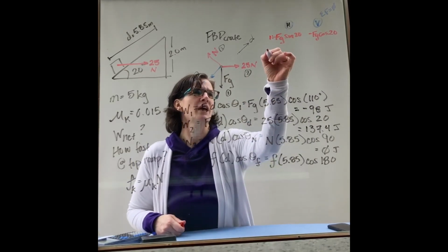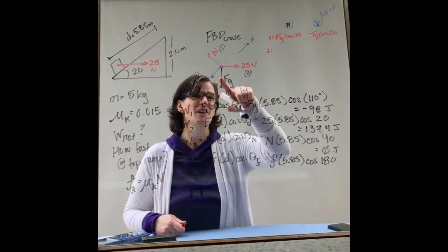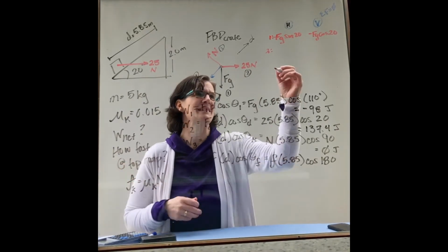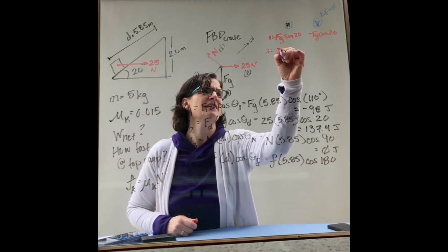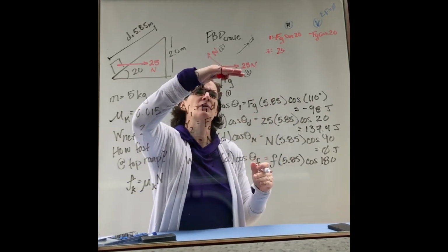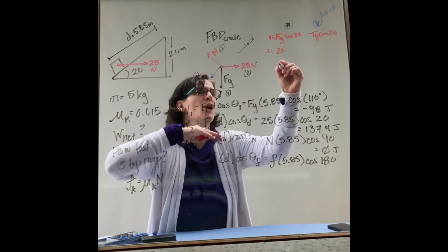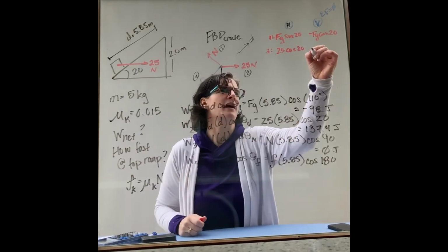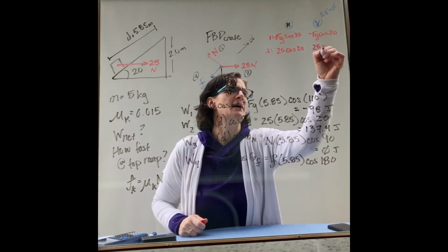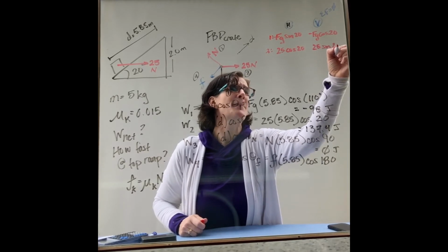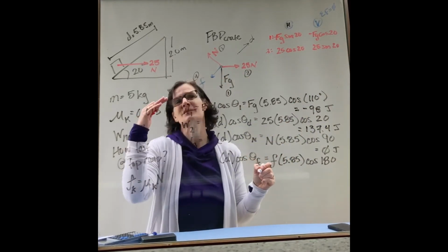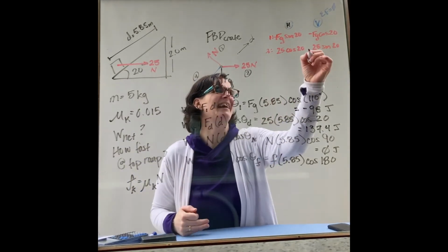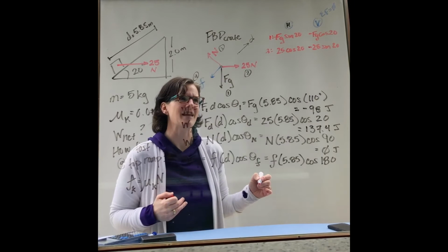Force number 2, that's the force that Doug's exerting. He has a horizontal component in the rotated coordinate system, 25. And if I think about how it rotated this direction, it's the cosine of 20 degrees. And in the vertical direction, we have 25 times the sine of 20 degrees. But in that rotated vertical dimension, the component for Doug is in the negative direction. So we want to be explicit about that negative.